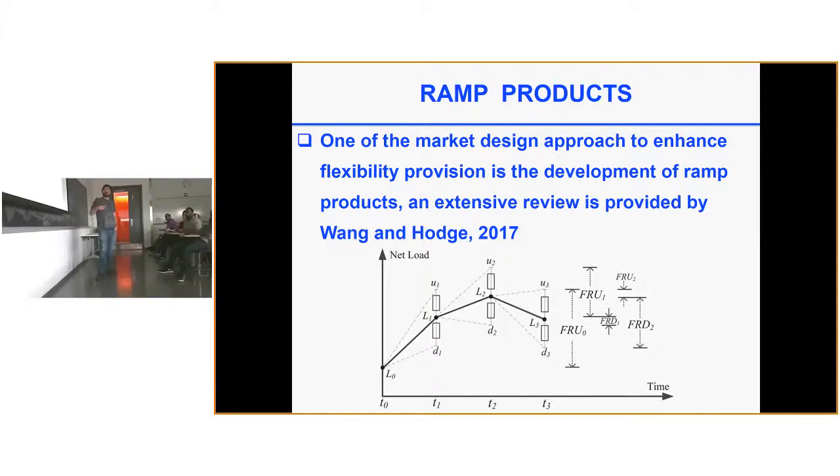So you say that if the load is somewhere in that area, we can meet it. One problem of this approach is that then thinking that you can be here and also here might not be realistic, because from here, you cannot ramp this much. You have to ramp at the same rate as you're ramping here.